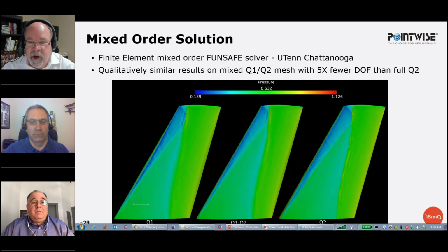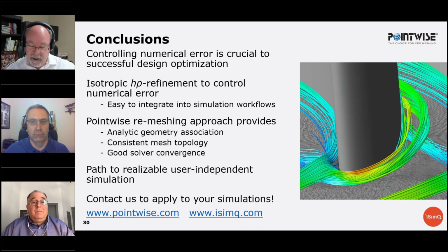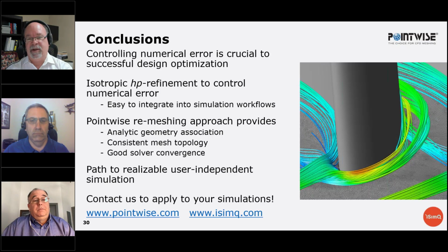So you have to adapt to the geometry. You can't adapt to the original mesh and have it be useful. You need your adaptation to take account that you already know about the boundary layer and preserve that mesh generated with the mesh generator rather than with an adaptation process. You need it to be robust, and you need the whole thing to be sensitive enough to your adaptation sensor so that it doesn't way overly refine and become not useful. So I would say, let's take some solid steps to go from the adaptations that have been out there for decades and haven't seen much use, at least commercially.